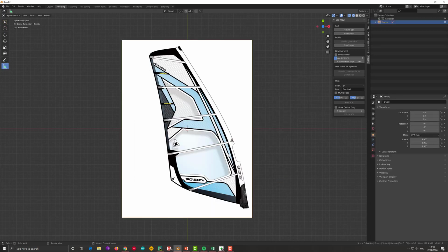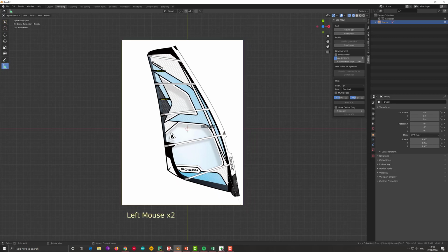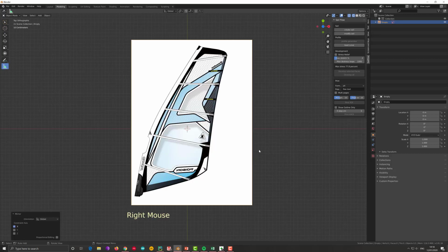Make sure the dimensions are correct. To do that, you go here where there is a measure tool, and for instance I measure the distance between the top and the bottom of the sail, which in this case is 4.7 meters, as you see on the screen. Let's assume this is a bit too much, it's probably not in the right dimension. I shorten the image a bit, resize it, and measure again. Okay, 4.3 is exactly what I wanted. Let's assume that. Okay, I erase the measure, and for this I want to mirror this image, because that's the way I like to work, with a mirrored image.